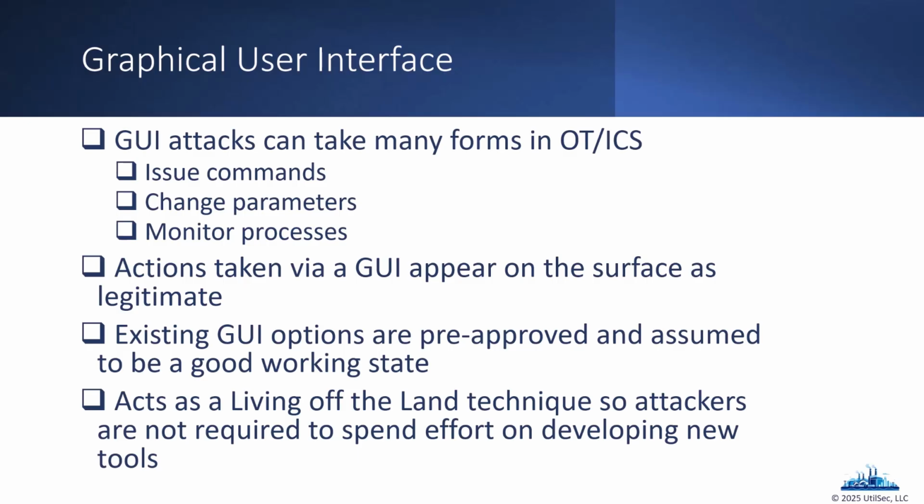GUIs that are available. Now, especially when we usually are talking about HMIs when we talk about graphical user interface. So you think the HMI is designed, right, not only to show us what's going on in the environment with the process, but to allow the operator to make changes, right, to interact with the process, to make changes that might be necessary essentially in an emergency, right?